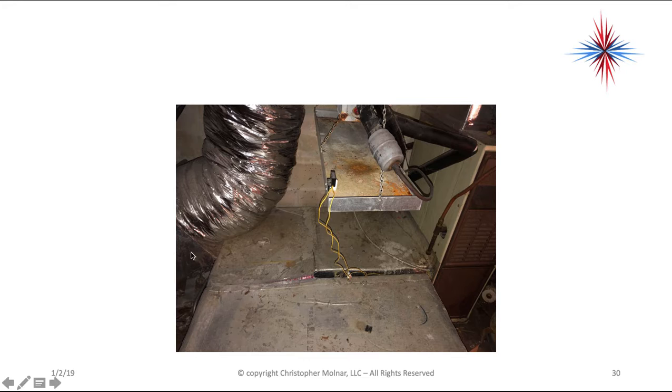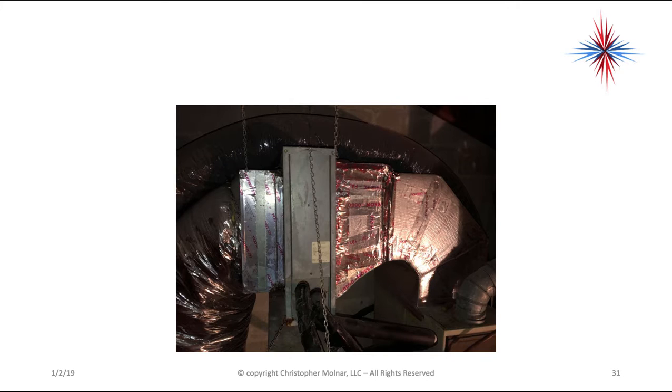Okay, and it's even more of a possibility when you look at the condition of the return plenum. Okay, this is all return plenum. It's all duct board. Okay, and over the years, you can actually see where people have done it. Tool bags have been sat on top of that ductwork. Okay.